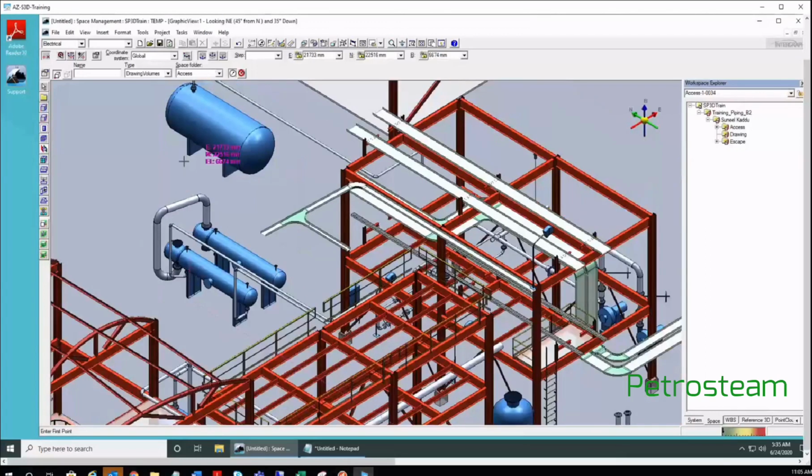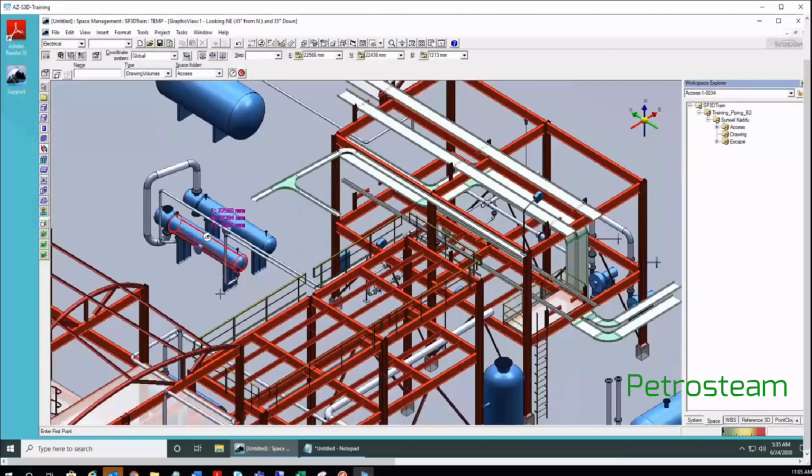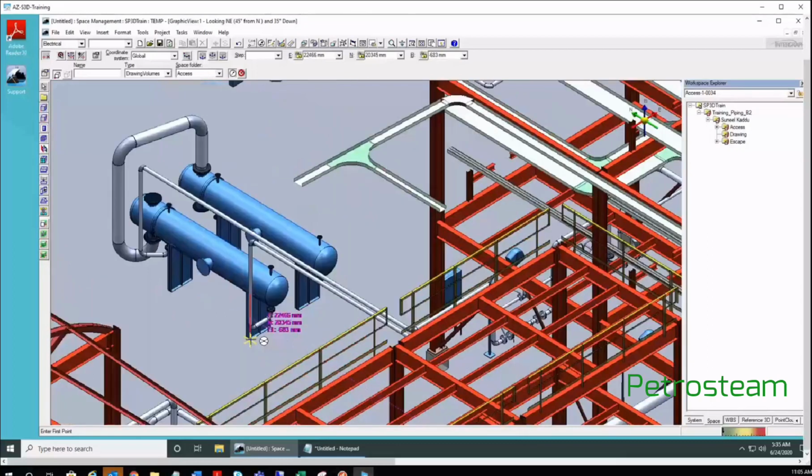Now, if you come near to this, you can just check its easting, northing, elevation. Okay. In the top pinpoint bar, you can see the easting, northing, elevation. Okay. So I will press F6 to input easting. This is 22,466.